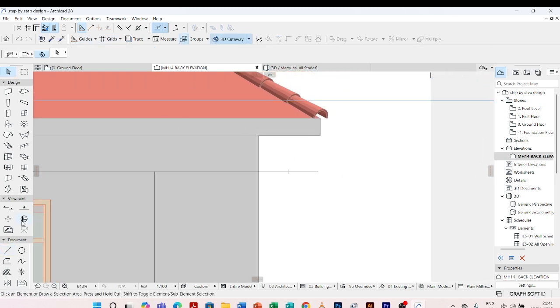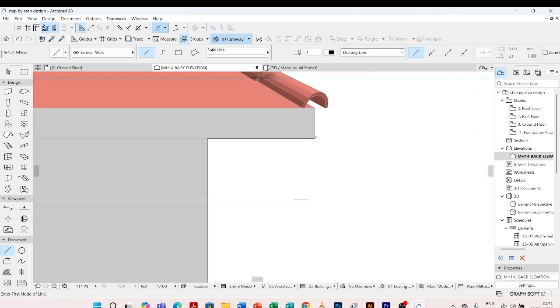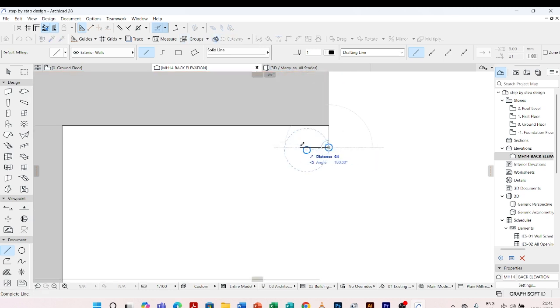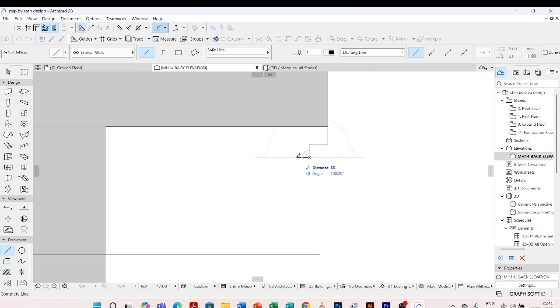So let me have the next line. I'm going to drop my profile by 50. I enter, then I move inside. Let me say still by 50. I move inside straight by 50. Then I'm going to move down by 35. Then I'll move inside again, let me say at 35 still. Enter. Then I'll have a straight line of 150.